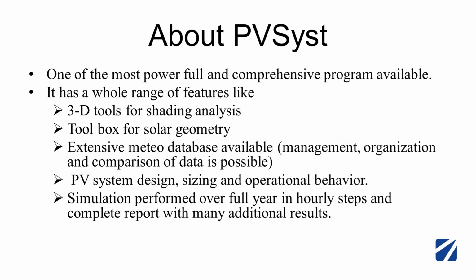Also an extensive meteo database. Whatever PV modules and inverters are available in the market, it has a database, and if you don't find the model in the database, you can get the file from the manufacturer, and you can just import it to PVSyst also.